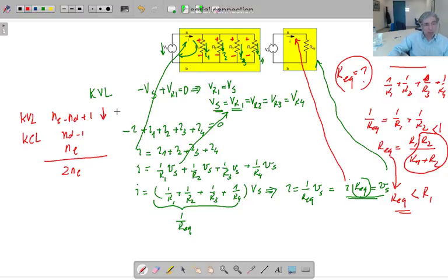So if you got more than one parallel connected element within the circuit, for each pair, the number of equations you're going to write is going to be less. So that means this number is reduced, this number is reduced, the number of equations that you're going to solve has been reduced. That's why it helps the analysis problem. Another thing is, if you got a non-available resistance value in the market, you might get it from the available resistor values. How can you get it? So maybe it is better to explain here. Anyway, you could do this.